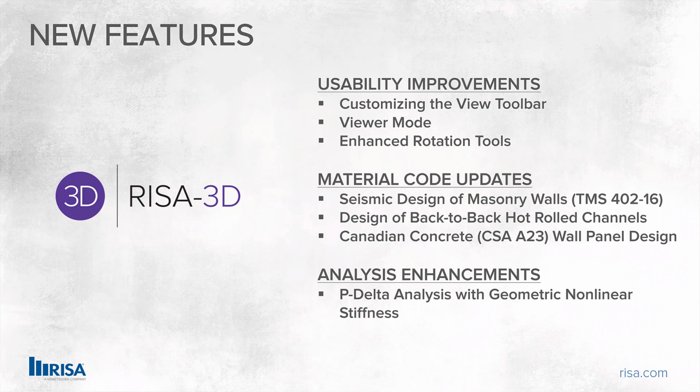In the past, if you wanted to look at P little delta in a RISA 3D model, you would put internal nodes along the length of a member so that the member would experience those deformations. This more robust analysis, rather than the more straightforward P-delta analysis that RISA 3D has included for a long time, will take over from that and give you a more accurate analysis.